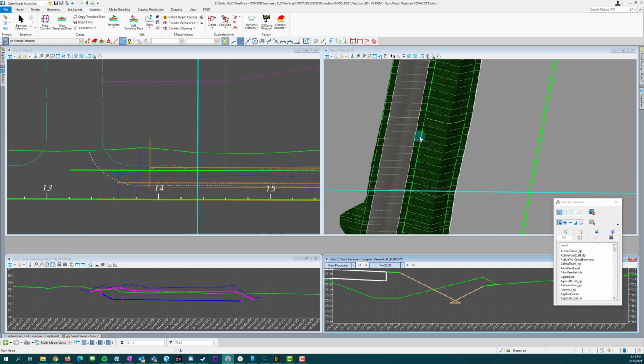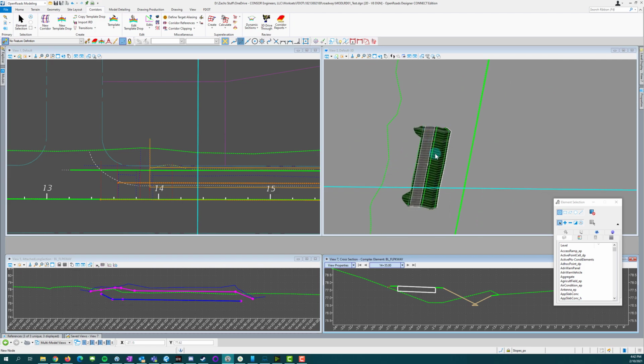So the other solution is to get rid of this profile and then change the template so that it's just a V ditch. So it just V's between these two locations. But that's all part of this process, is trying to get all of these things to balance out. That's why it's interesting when people are saying, "Oh, it's just a sidewalk job." Well, this is the hard part of the sidewalk job, is getting something to fit somewhere where it really doesn't. And it can be difficult and frustrating, but if you use these tools, you should have some pretty good success.